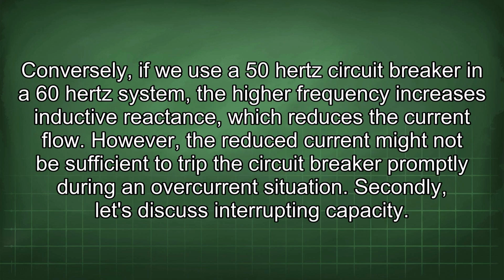Conversely, if we use a 50 Hz circuit breaker in the 60 Hz system, the higher frequency increases inductive reactance, which reduces the current flow. However, the reduced current might not be sufficient to trip the circuit breaker promptly during an overcurrent situation.